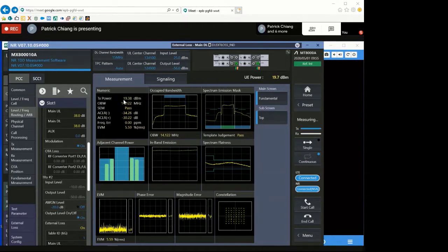The requirement, I think, is 19 dB, the lowest limit. So the path loss does matter for the power value you measure. If you do conducted, then you need to compensate for the cable loss as well. And this number needs to come from your vendor or OEMs.